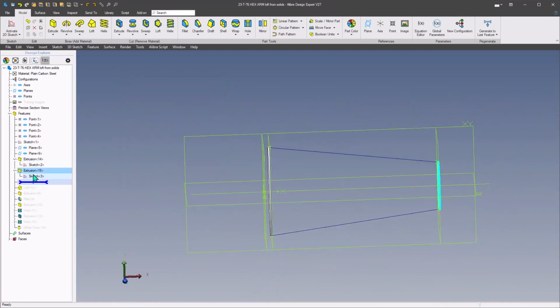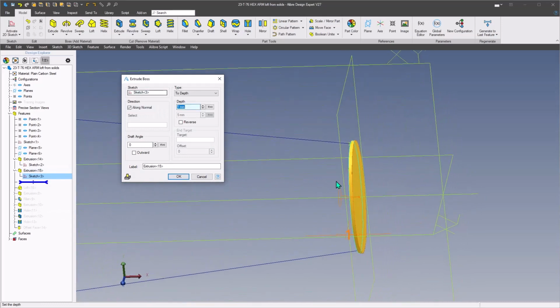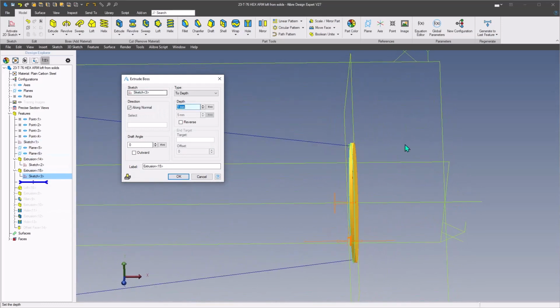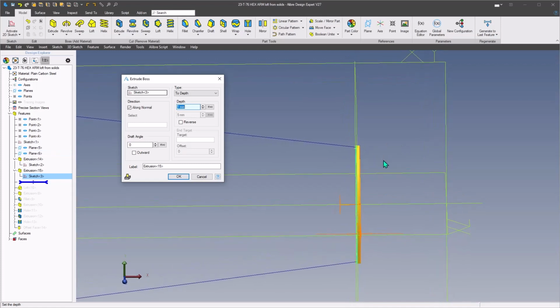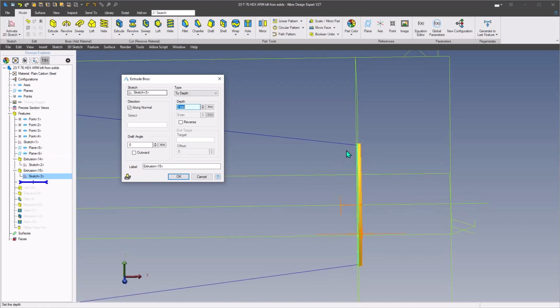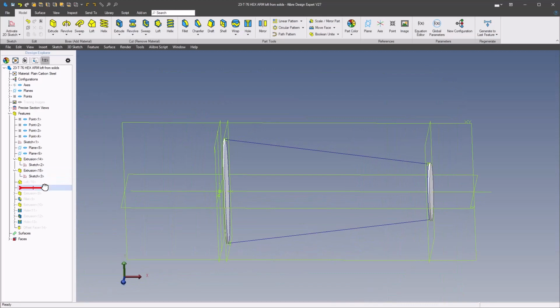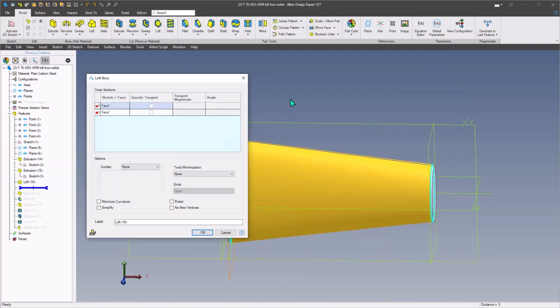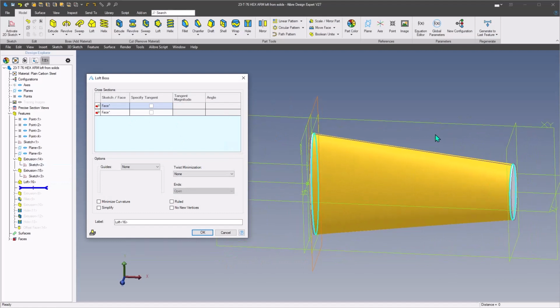On the opposite end, I created another extrusion on that ellipse, and again it's 1 millimeter thick. In this case it wouldn't matter going either direction, because if it goes to the left it would be going inside the loft parameters, because it ends up being smaller than the angle of the loft. Anyway, once that's selected, I created the loft, selecting the two opposing faces of the solids.